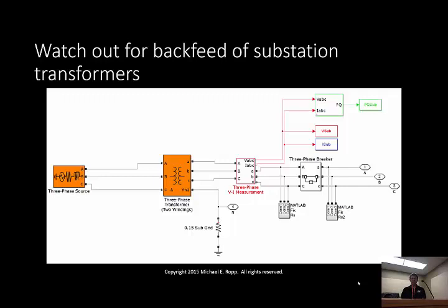I wanted to show you this case, too, that I mentioned before. If your DG is on the grounded Y side of a transformer and there's a delta on the other side, then you can have a ground fault over voltage on the delta side. And where we used to see this all the time was with existing facility transformers. You'd put a PV plant on the Target store. The Target store's facility transformer was delta on the high side to isolate its fault current concerns from the utility's fault current concerns.